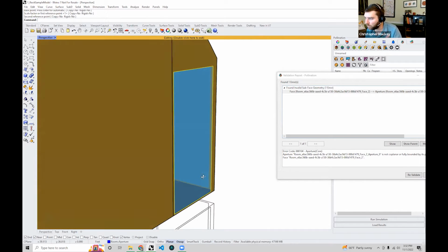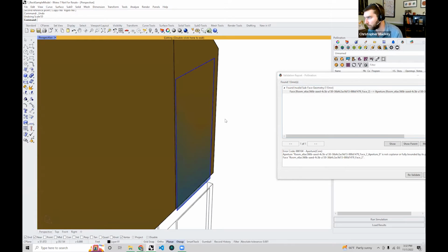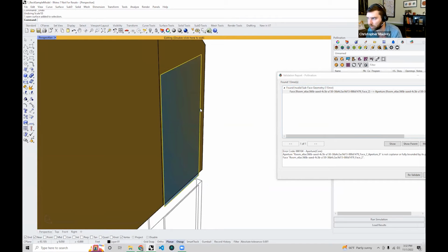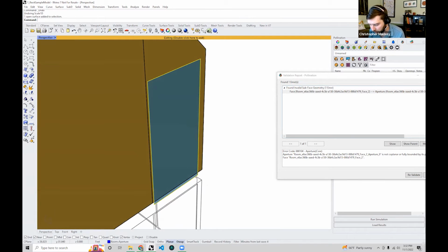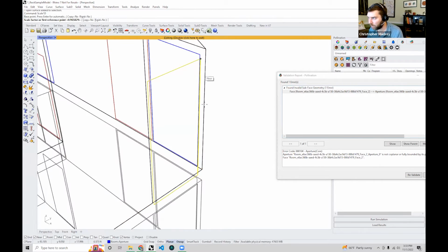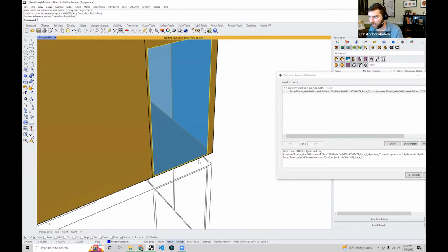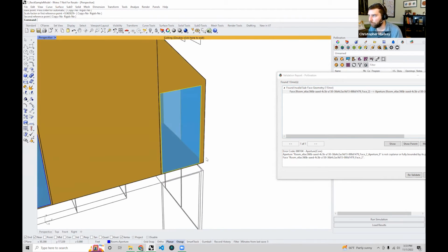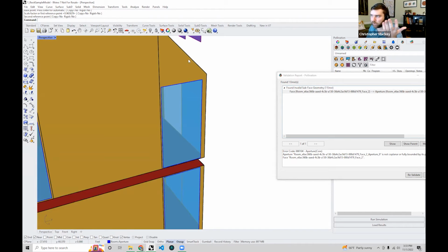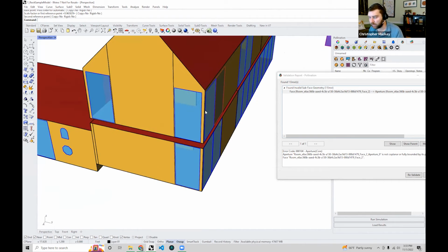So once I've scaled 1D like this, maybe I'll just show this again because some people, this may be the first time that you're using Rhino, right? Just make sure you have this aperture selected, type scale 1D, hit enter, and just select the upper right corner, the lower right corner, and then the neighboring adjacent endpoint. That'll make sure that you've scaled it into that correct point there. Then you can double click up top here to exit this room editing menu.